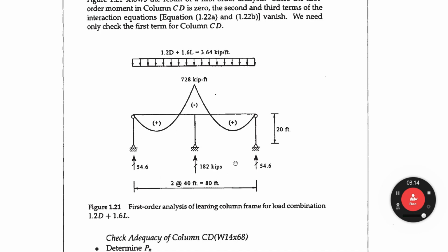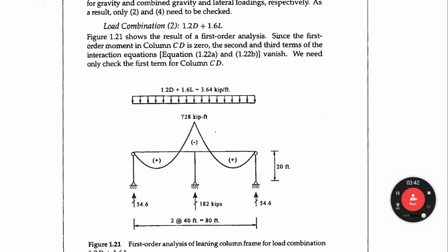The exterior column reaction is this one. So it is some reaction. That means the column axial force. Okay, we calculate column strength. So compare these two values. Column strength must be greater than this axial force. Then we can say this is safe for this loading case, right?